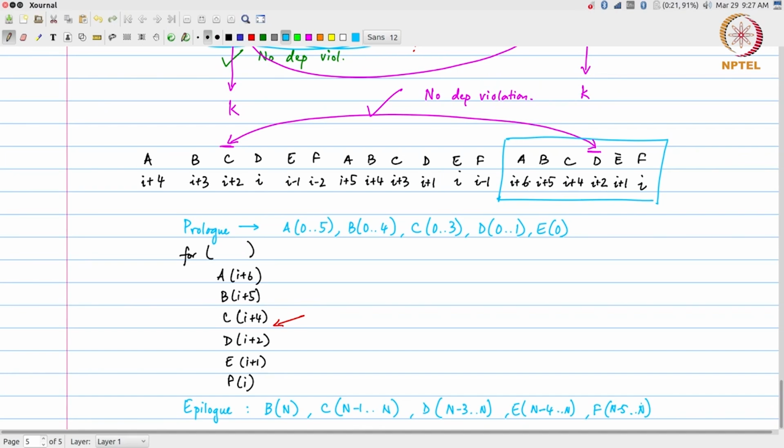Okay. As long as I have done that, effectively what happens over here is, this is the loop body which gets an initiation interval of 6. Given the circumstances, given the hardware that I have, that is the best possible initiation interval that I can target, right, because at any given clock cycle I can only initiate one instruction, one function. I have 6 functions to do, therefore, I need at least 6 cycles in order to complete one loop body initiation, right.